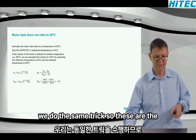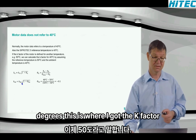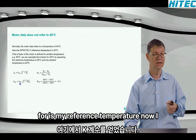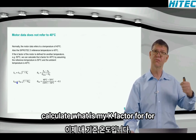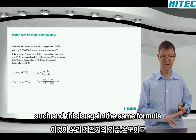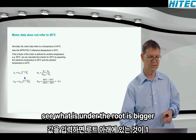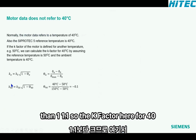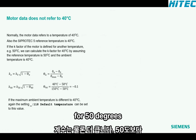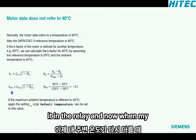We do the same trick. So these are the formulas you know already from the slide before. And now we say, okay, the 50 degrees, this is where I got the K factor for, is my reference temperature. Now I calculate what is my K factor for 40 degrees because this is the reference temperature for our relay as such. And this is, again, the same formula. So you put in the values and then you see what is under the root is bigger than 1.1. So the K factor here for 40 degrees is bigger, of course, than the one for 50 degrees. Okay, then I take that K factor and set it in the relay.